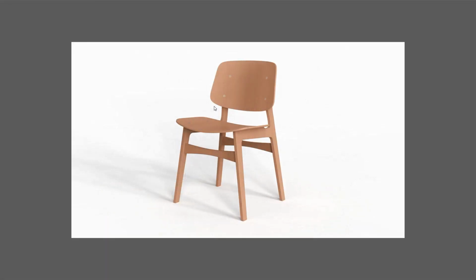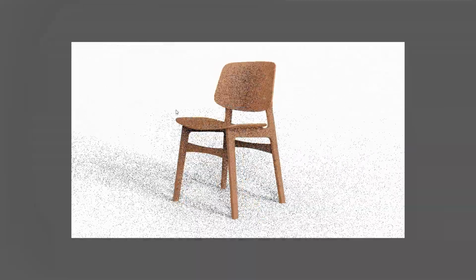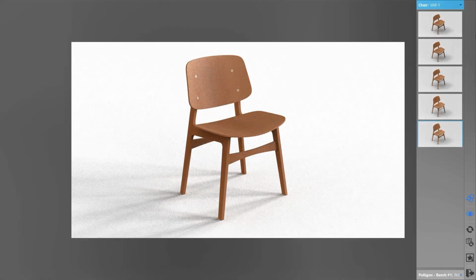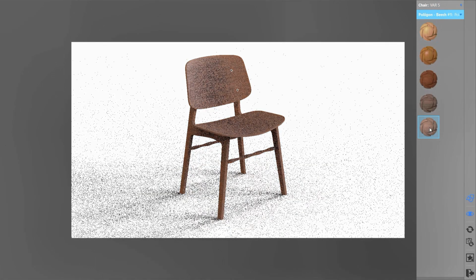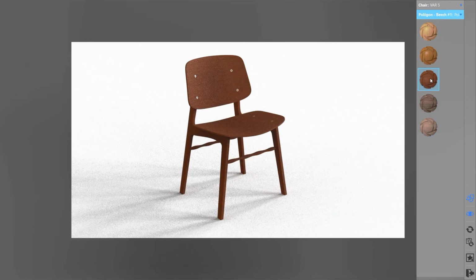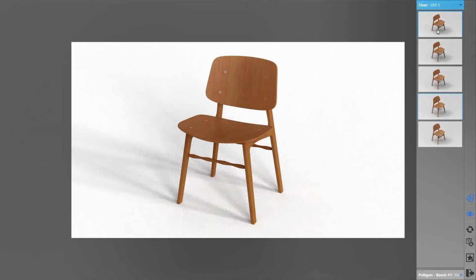So the next stage I've got in the design process is the approval stage. This might be where you want to showcase your models to stakeholders or other colleagues or clients, and you want to show them rendered what the final image might look like. Within KeyShot, there is what's known as a configurator where you can set it up to display all your different models, which they can toggle between, as well as any materials that the product may come in. The beauty of the configurator is that the end user isn't just seeing the KeyShot interface, so they are not bombarded with the entire library of materials and tweaking your model that way.